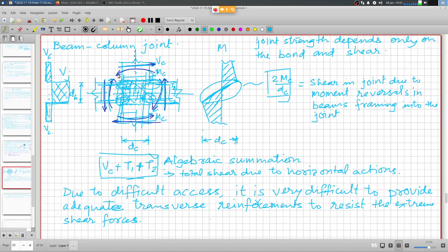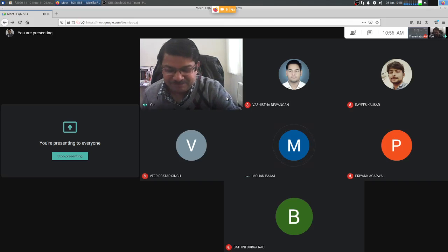So let's say it is the column's moment, that's right. So we are drawing the column, we are approaching this joint from the column, but I could have approached this joint from the beam as well, isn't it? I could have drawn the bending moment diagram like this, right? So it will be the same thing. So the considerations are same.